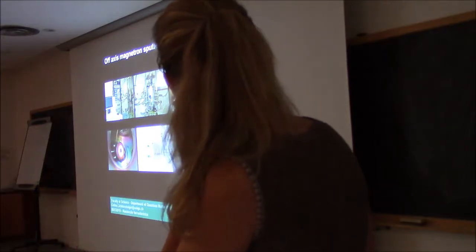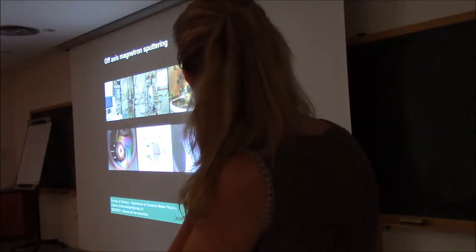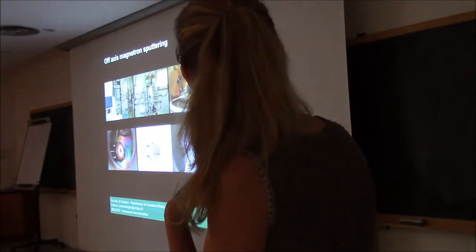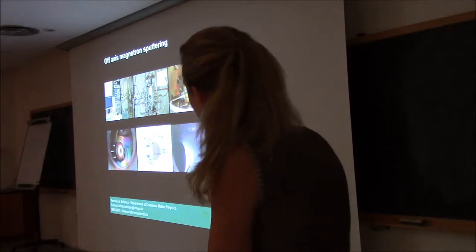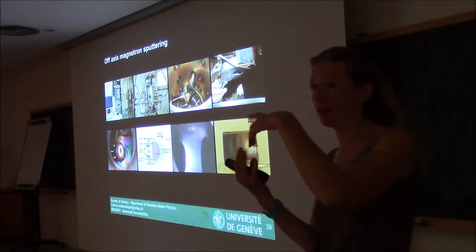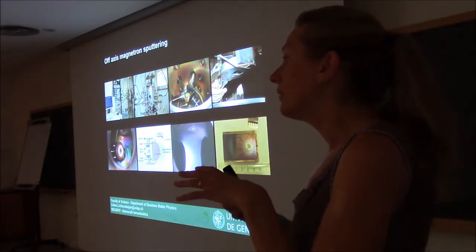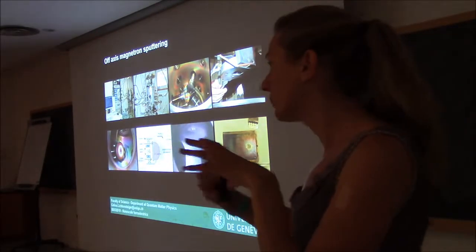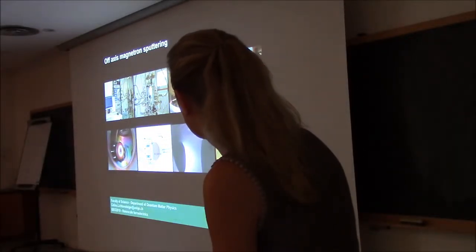You have a vacuum chamber. You have different guns here inside the chamber. So the idea is that on each of the guns you have a target that contains the materials that you want to deposit in the form of a ceramic material. And then what you have to do is find a way to remove the atoms from this ceramic target and to put them on the substrate that is positioned here.